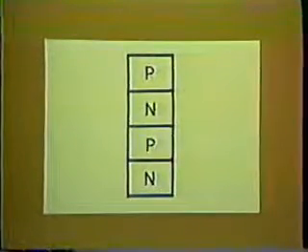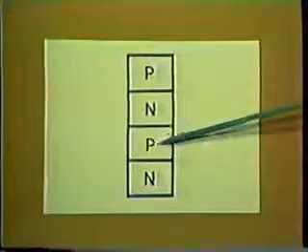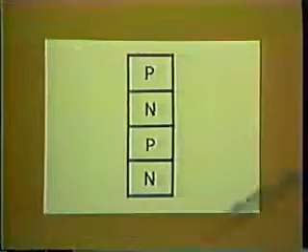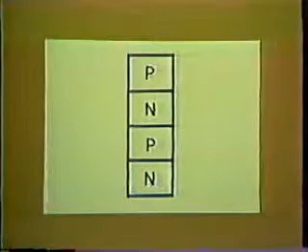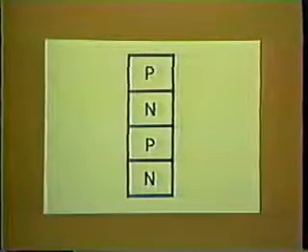Now we'll look at some semiconductor devices that have 4 layers, 2 layers of p-type material and 2 layers of n-type material. This 4-layer arrangement gives us 3 p-n junctions. There are numerous special semiconductor devices in this p-n family, but the most common one is the SCR. The SCR is used in control circuits to control the amount of current or voltage applied to a load. It is called a silicon-controlled rectifier because it is a rectifier which is controlled and is made from silicon material.